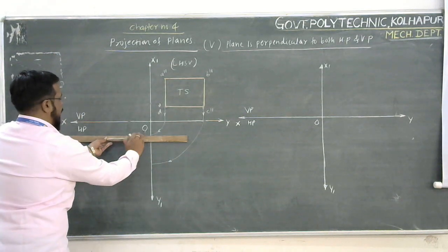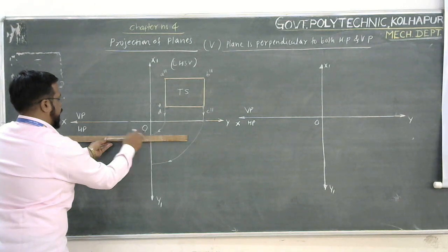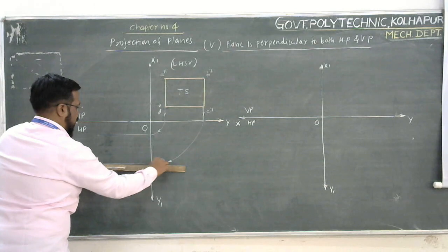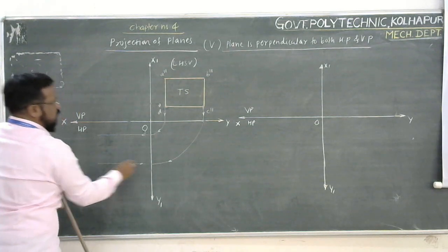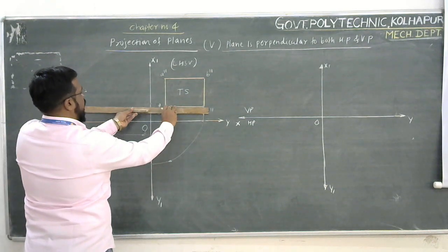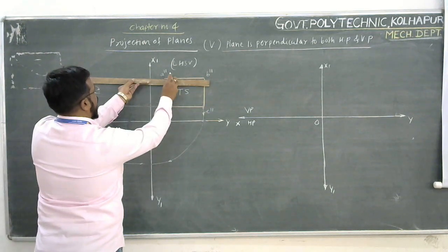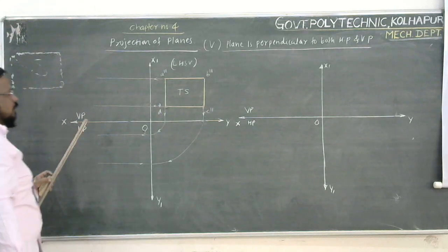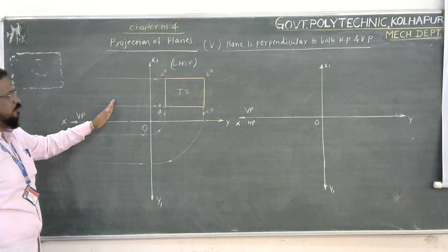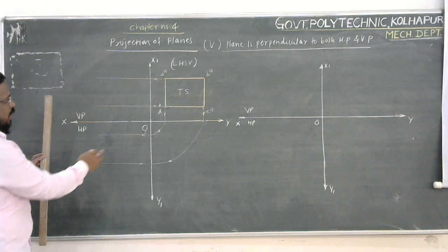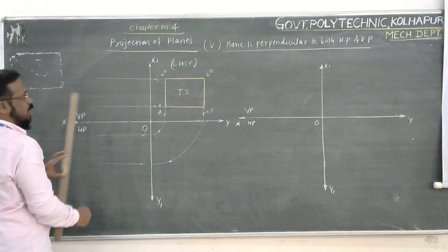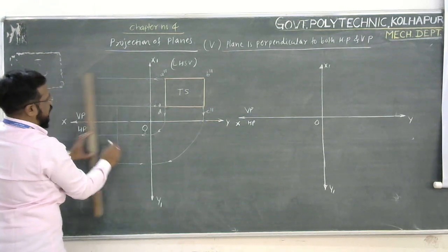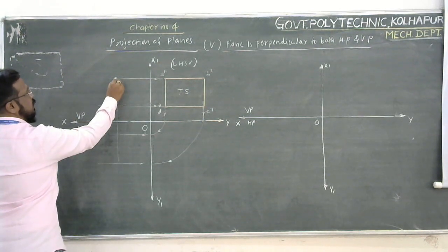So I will draw a line here. Similarly, the side view is projected to the front view. So it is projected backward like this. So here I may get the front view in the form of a standing vertical line, and the top view again in the form of a vertical line. So I have to draw it anywhere in this space. You can draw this projector. So this will conclude that this is the point.